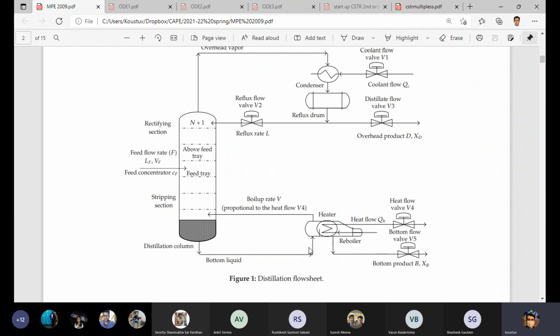See, let us start from the mass balance or mole balance at least. So we have F equals bottom products, that is B, plus the distillate, that is D. We also know this under the condition of continuous steady state behavior.